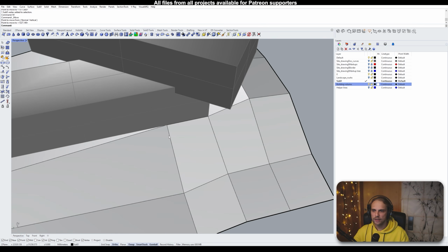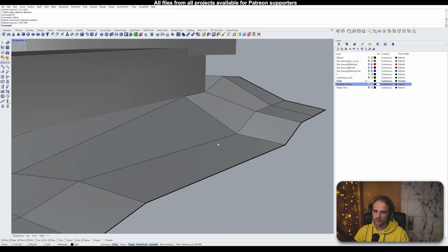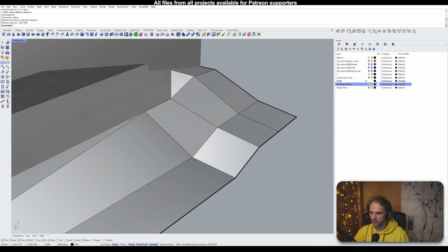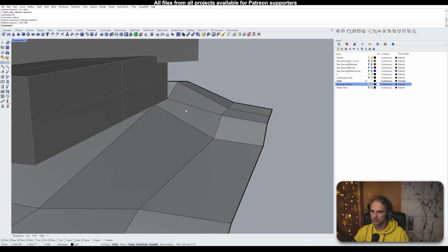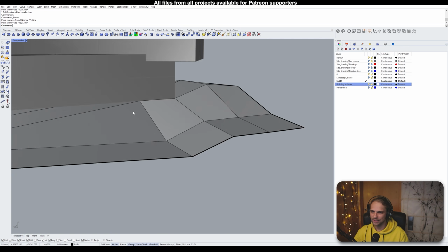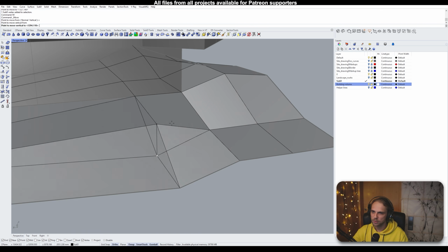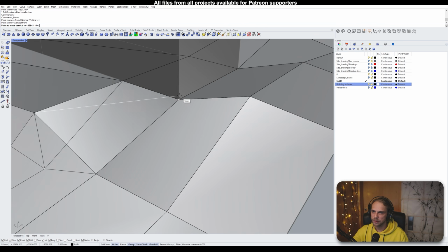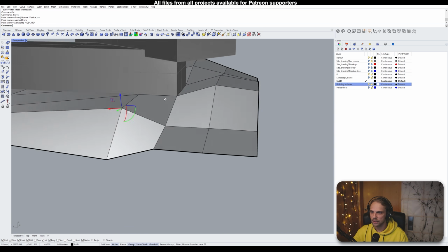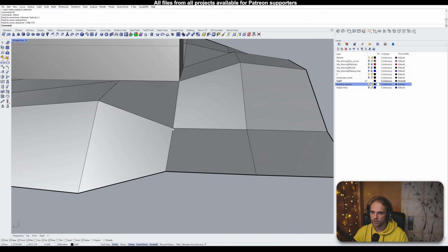All right, I said that here I want a terrace that should be flat. Well, by no means should this be considered flat. So I will take this point and I will M, enter, V, enter, move, enter, vertical, enter, from its original position to the same height as my building bottom corner point, like that. I'll repeat it for this point as well.